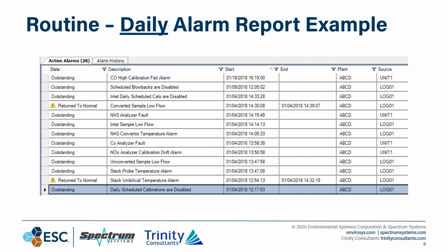Yeah, I'd like to point out in the control room, I've seen two different environments. I'm sure you've seen this too, Steve, being in power generation, that if your alarm is annunciating in what I'd like to call lighted up like a Christmas tree with commingling operational alarms, you might get lost and you might have nuisance alarms that desensitize you to the environmental alarms. So that's one scenario I've seen. The other scenario is where you have a dedicated DAS screen that lights up at you. It's unique, it's individual, and you can quickly see that you do have emissions monitoring problems.